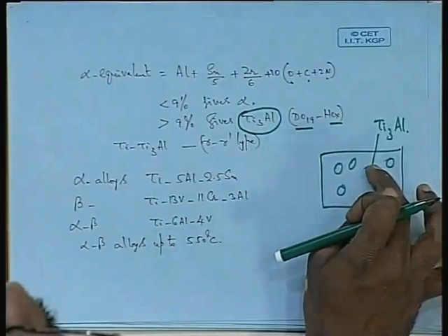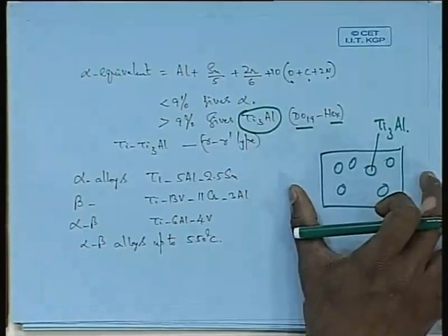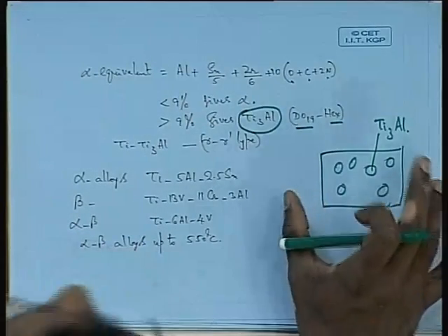If we can convert the DO22 structure or DO23 structure of Al3Ta and Al3Zr into an L12 structure, from tetragonal to cubic structure, which we have shown examples of, again you have an ordered cubic structure, ordered particles in a disordered cubic matrix. So all these are examples which are similar to the gamma gamma prime type of nickel based superalloys, and you can get much higher strength. Only thing is here, because the hexagonal matrix is there and ordered hexagonal particles, the formability here is not very high. One has to remember that, but one can use this.